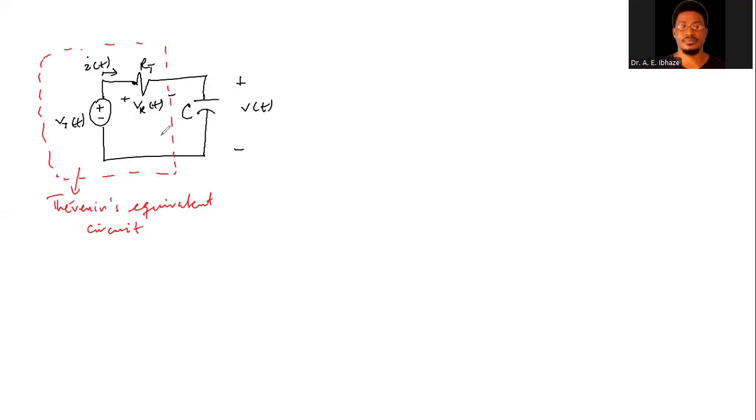Okay. So meaning, should we have a number of resistors in the circuit, we could resolve to come up with an equivalent resistance connected with the voltage source as the Thevenin equivalent circuit, and then connect in series with the capacitor, which still forms the RC circuit.